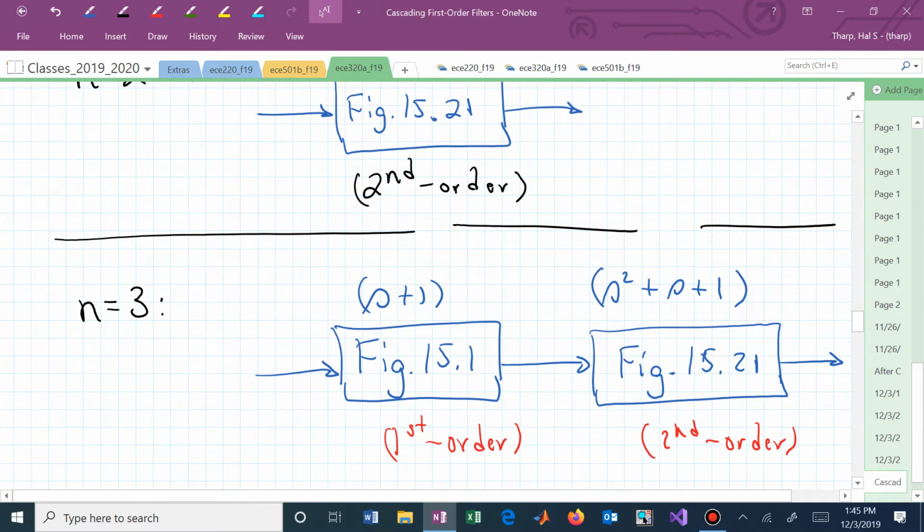We expand that unit circle to a circle of about 1,000 because that was our K sub F. That's how far they are now into the left half plane. And they stay at the same angles, orientation-wise, as in the normalized case. Questions now on filter design? If you have them, let me know, but I think we're maybe getting a feel for filter design.